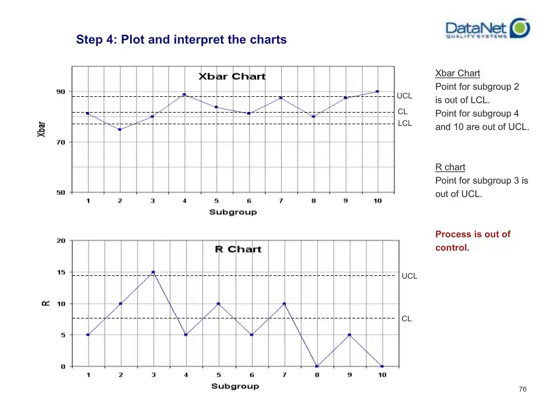However, your X-bar chart is showing you that while that may be the case, the averages of those values themselves are still straddling, or are beyond, your upper control limit. Your process itself looks like it's changing and it's out of your historical control. Doesn't necessarily mean it's a bad thing, but it is something you absolutely want to investigate and find an assignable cause for.